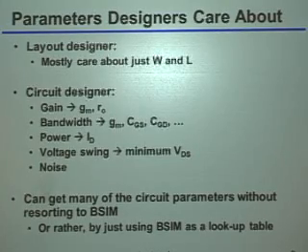It's usually that the width and length are something you calculate or decide based upon these other specifications that you're interested in. In fact, even inside of these specifications, if you looked at the underlying device parameters you really cared about, I would claim you don't care about width and length. You'd care about other metrics. With gain, you'd care about the transconductance GM and the output resistance RO.